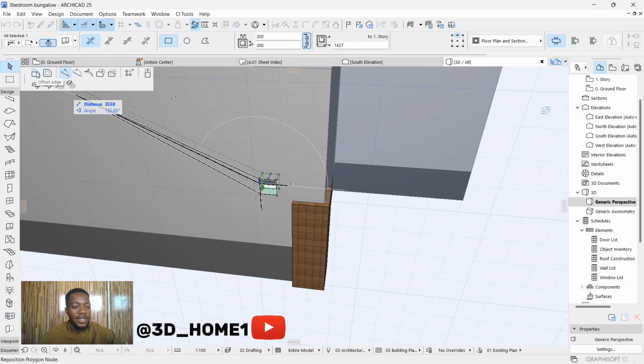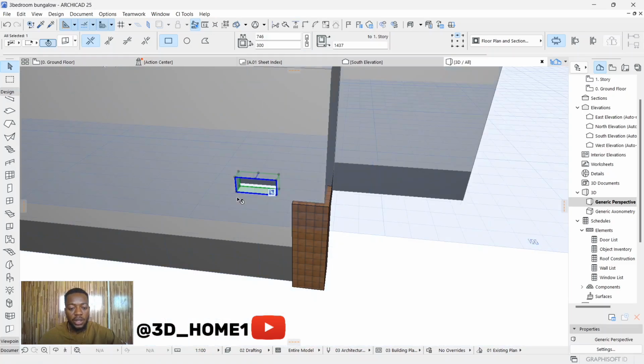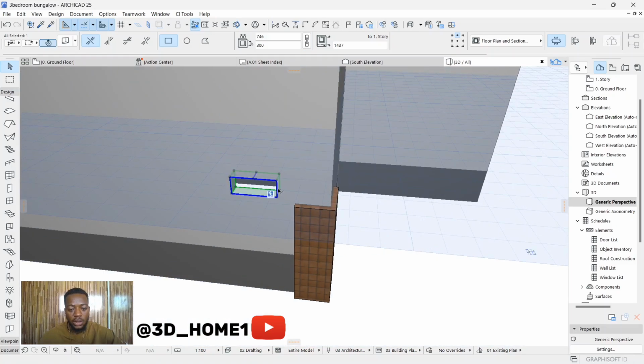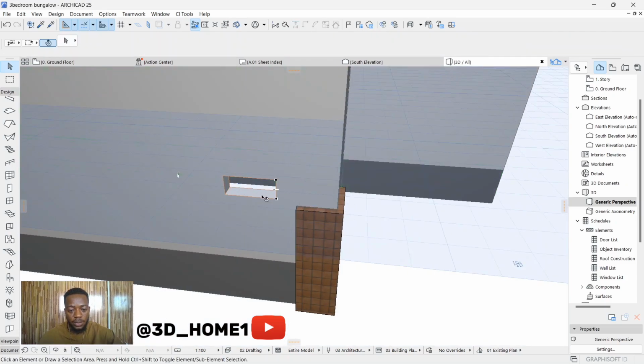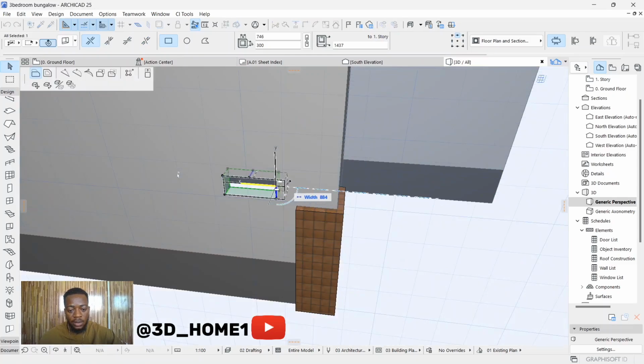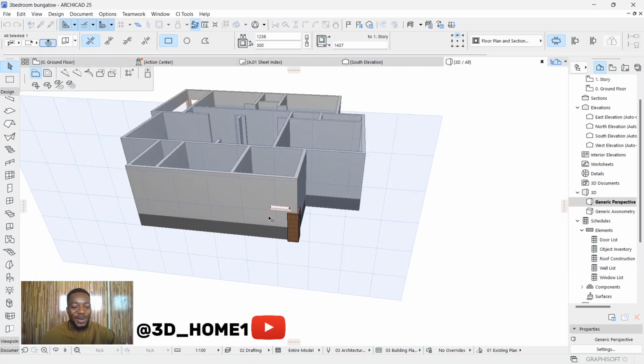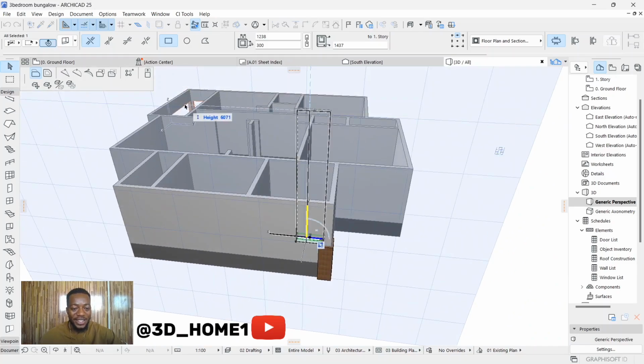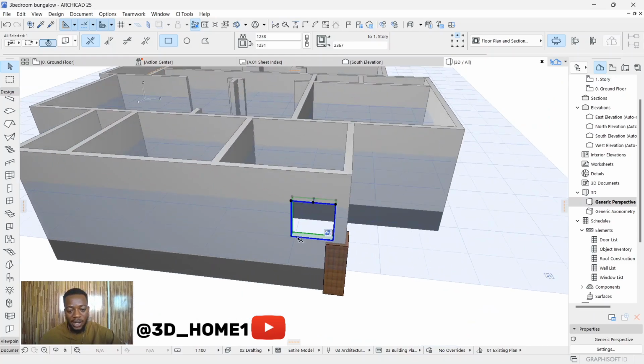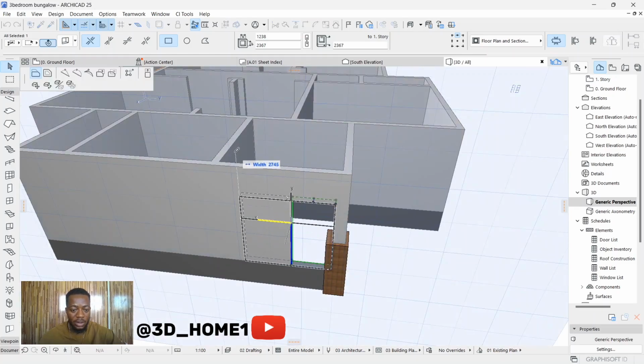Okay, and select offset edge. Now you can drag this one inward. The blue line, that's what you must click on after selecting the slab on the wall and the opening. So now let's align it with this other one. Then let's take this one down to DPC, then take this one down to this point. This is how big this porch is.